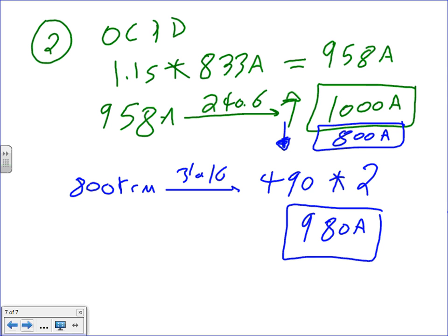So that's why a lot of people, when you go that high, first size the overcurrent protection device. If you are higher than 800 amps, the best way to do it is always do the overcurrent protection device and then size your conductors to match it. Any question, guys?